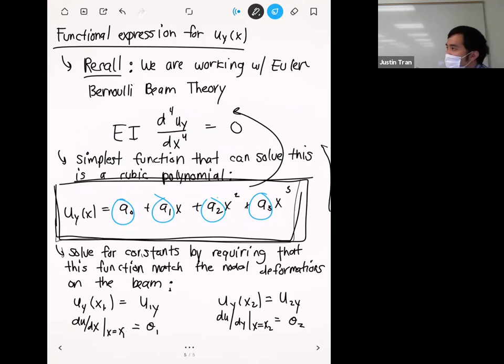Yeah, it's not a compressive strain, because compressive strain would be dux dx, but it's a shear strain because we're taking the derivative of a transverse displacement with respect to a perpendicular direction. And then you would do it in both directions. Yes. Okay, thank you.